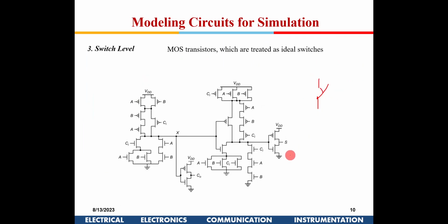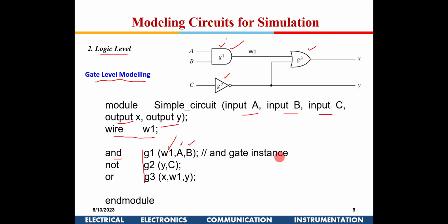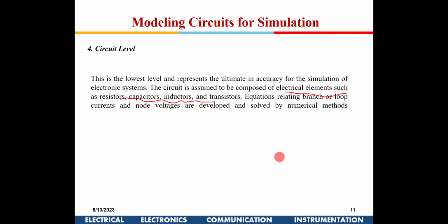There is no point doing a transistor level in the beginning itself, because here the failure could be because of the sizing of the transistors also, which it will not take into consideration at all. So first you do this and clear your test run, and if you find this is working fine, only then we move to the bottom.